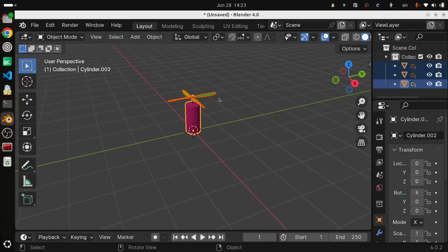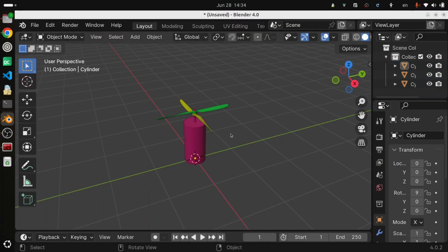Now I have my file in this older version, and I'm going to export my objects as Collada using this version. Because I want each part of my model to behave independently in Gazebo, I don't export the whole assembly at once. I export each piece individually.